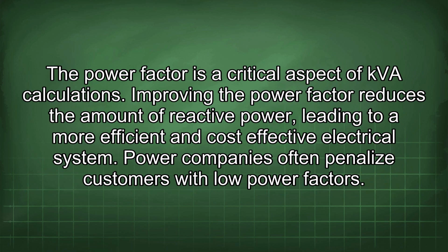The power factor is a critical aspect of kVA calculations. Improving the power factor reduces the amount of reactive power, leading to a more efficient and cost-effective electrical system. Power companies often penalize customers with low power factors.